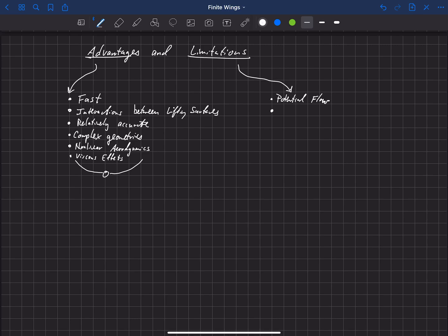This is also not very accurate for low aspect ratio wings. Okay, so one of the main assumptions built into this is that the vorticity that would be distributed along an airfoil is all coalesced at the quarter chord, where we're placing this lifting line. So if you look at this cross section of a wing, we're placing all of this vorticity here at that location, gamma. It can't account for these chordwise effects. Actually that vorticity is distributed along the airfoil, and we're lumping it all there at the quarter chord. And so that's more accurate for higher aspect ratio wings.